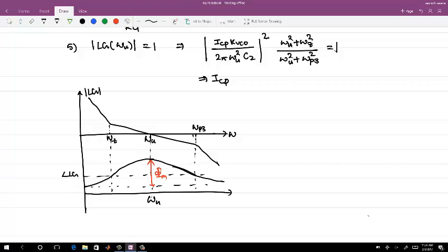That's what I was just saying, the same thing. I have not done anything on the ripple suppression part, right? But I know the second pole placement is doing something for the ripple. So now if I change my phase margin, then my omega p3 placement is going to change. Then my ripple is going to change. So you can say for the ripple suppression, there is a placement of the second pole.